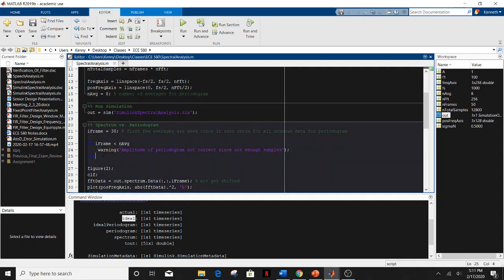So for example, if I were to look at frame 1, I would have read in 1 frame of data, and it would assume that I have 7 previous frames of zeros. And so the amplitude I see will be 1/8 of what I would expect. And then for frame 2, it will have frames 1 and 2 of data, but it will have 6 frames that it assumes are zeros. So my amplitude will be about 1/4 of what I expect.